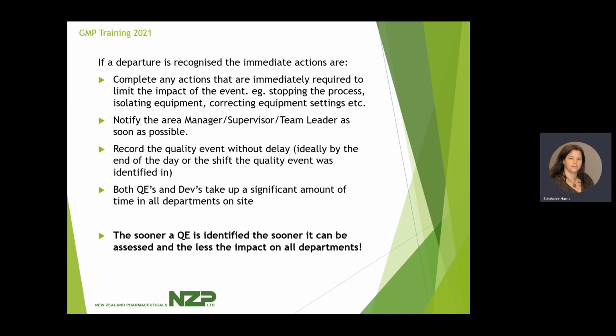If a departure is recognised, the immediate actions are: complete any actions that are immediately required to limit the impact of the event, for example, stopping the process, isolating equipment, correcting equipment settings, etc. Notify your area manager, supervisor, or team leader as soon as possible. Record the quality event without delay, ideally by the end of the day or shift the quality event was identified. This is done through the QE log.